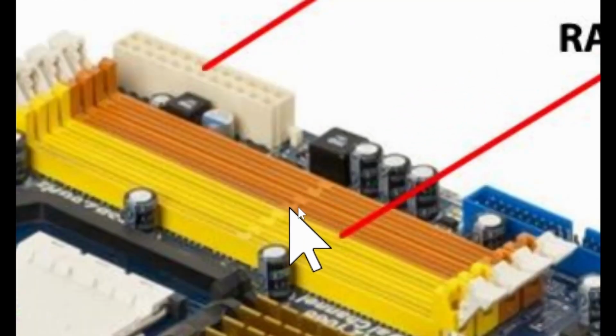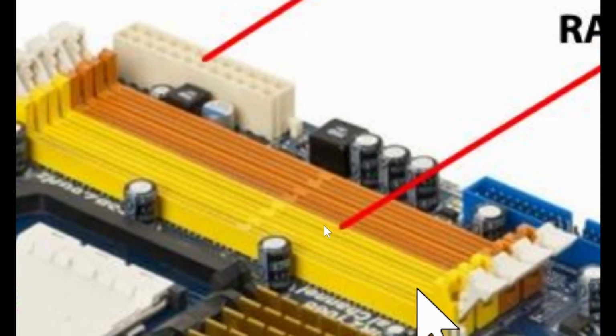Over here, do you see something here? Good. If this motherboard supports DDR3, this barrier here will be placed at the right place so that a DDR3 RAM can be inserted into it. Because if this motherboard is DDR3, this is exactly where the notch is. It is not somewhere here or here.